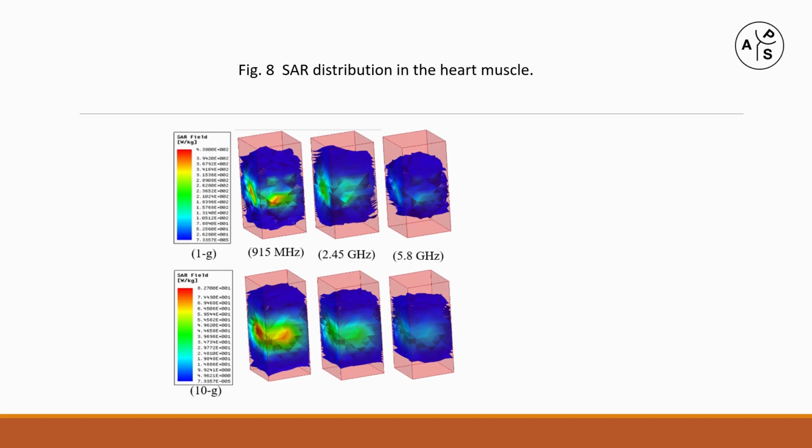The maximum input power requirements for the proposed antenna are only 3.65 and 24.18 milliwatts for 1 gram and 10 gram SAR. Hence, the proposed antenna is safe for long-term operation in the human body.